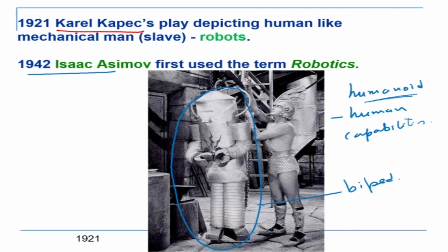But it took us very long to come to biped, essentially because wheeled robots were the earliest robots. Why? Because if you have 4 wheels, this doesn't require balance. The robot is balanced already. So if you just leave it there, it stays there. If you rotate the wheel, it goes forward. So control is simple. In terms of energy efficiency, it is simple.